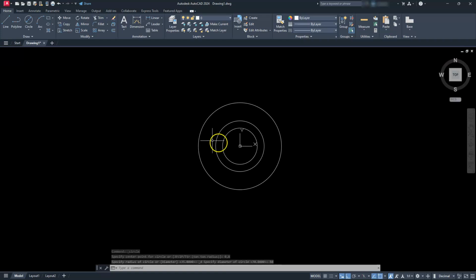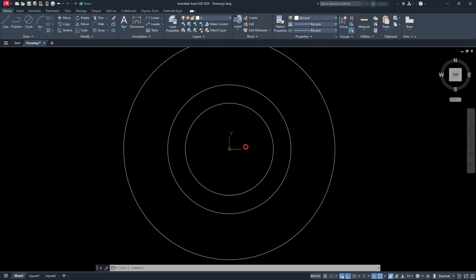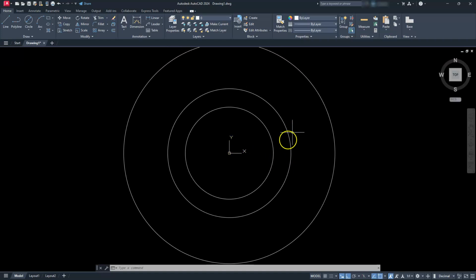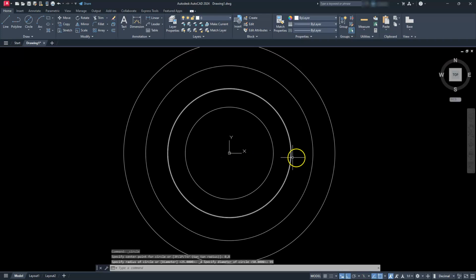All right. Few more things we can do on this view here. Let's create our circle that's located here. Now this one is on a bolt circle that's at 95 as the diameter. So if I create a circle center diameter from 0, 0 and the diameter is 95, I have located where I can place those 2 circles.